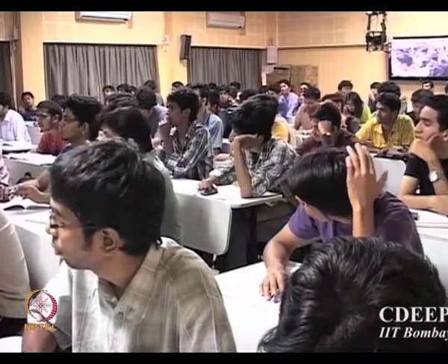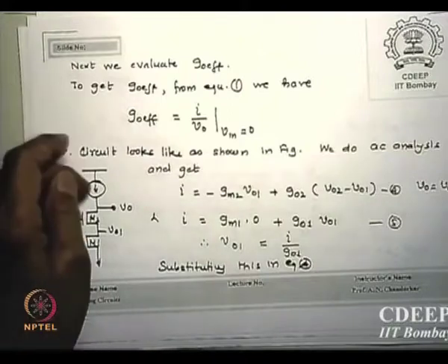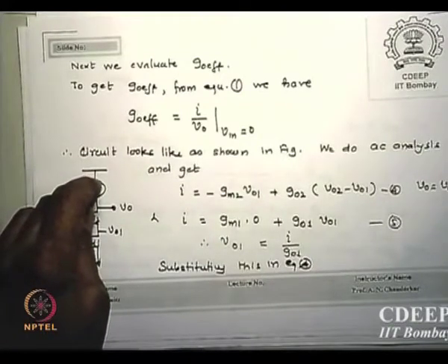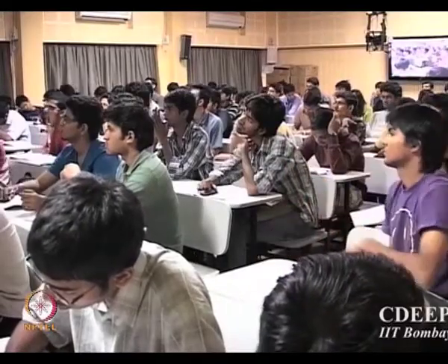M1 AC signal is grounded, but bias is not removed. Bias is coming from I. I have already told you that I is equal to beta by 2 times (VGS minus VT) squared. If I keep I fixed, I am keeping VGS minus VT fixed, which is biasing it for saturation. Is that clear? I repeat, you have not got my issue. Any time I say I is fixed, please look at it the way I say it now, once and for all.